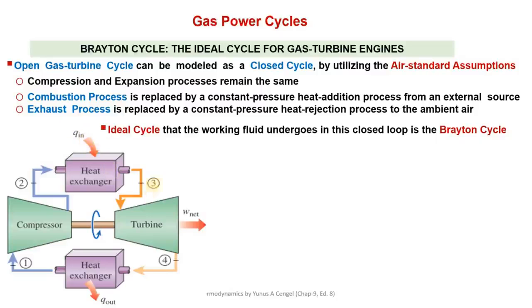And the maximum temperatures in case of steam turbines is around 500 to 600 degrees Celsius. So several steam turbines are often arranged in a row. We have seen that in case of steam turbines, the turbine actually consists of 3 stages: low pressure stage, intermediate stage, and high pressure stage, so that we can extract the power of this steam in a more efficient way. But in case of gas turbines, on the other hand, they rotate directly in the hot combustion